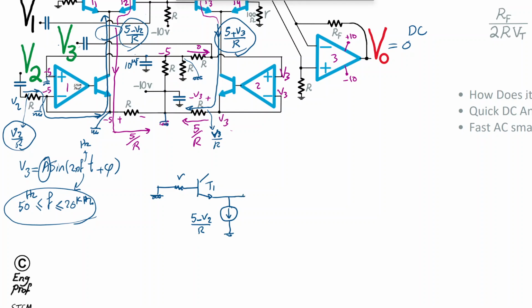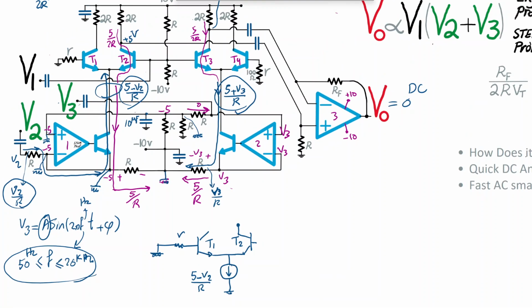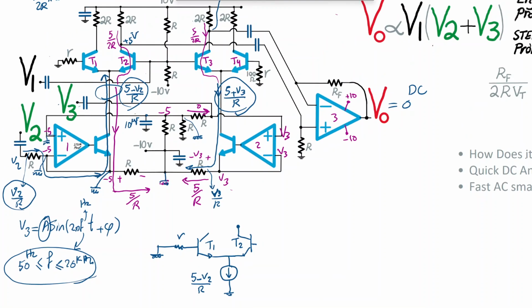And then we have transistor T2 and the desired output. The desired output is what? And then it's grounded on the other side. In the sense that we don't care what is going on on the other side, because on the other side we have the parallel of these two resistors, since on one side is virtual ground and on the other side is virtual ground.